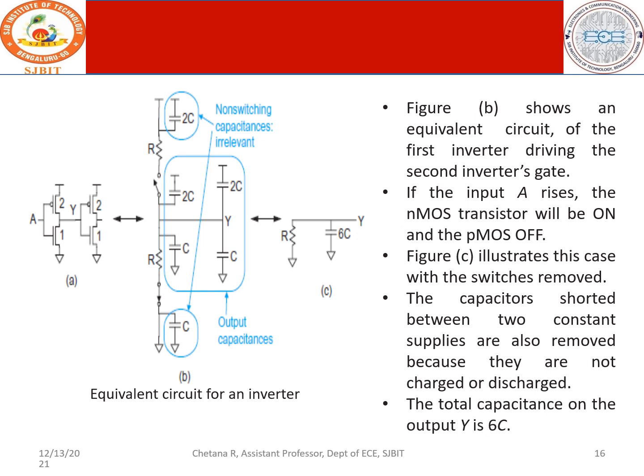As I told you, gate capacitances are connected here, therefore you have gate capacitance here as well as here. Okay, let me show you. You will have gate capacitance connected here and here as well. Since the K value here is 2, the gate capacitance will be 2C and 2C. Next, source also has one capacitance. Since the respective PMOS width is 2, it will be 2C. Since the diffusion is also a capacitance, it will also be multiplied by 2, and it is 2C. So this is with respect to the first stage.